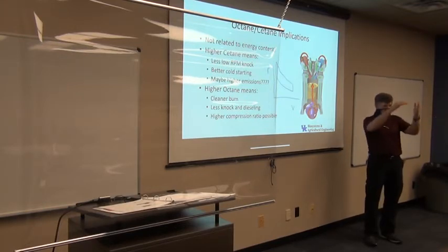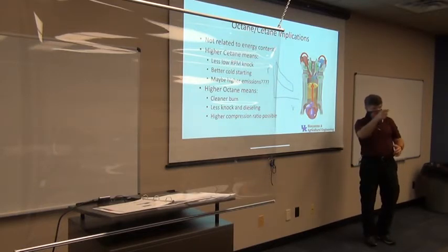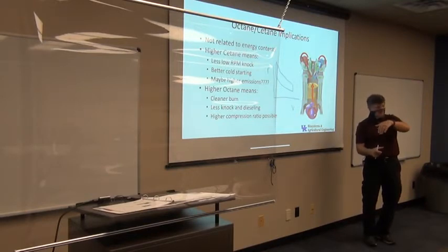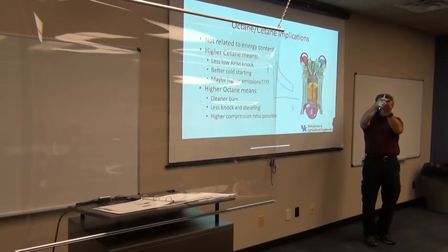Intake. So we've got to get fuel into it. On a 4-stroke engine, the piston comes down and pulls in either air or air and fuel. Then what's next? Compression. I compress the fuel. What happens after I compress it? Power. I ignite it. So I either inject the fuel in compression ignition or I hit the spark and light it. And then I've got the power stroke. And what's the last one? Exhaust. I shove the old gas out and then I start all over again.